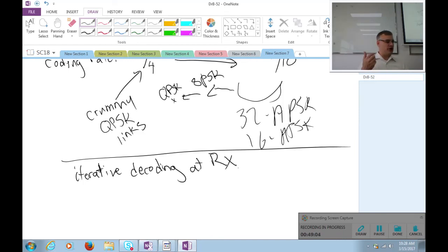And then if you apply your error detection and say, well, I definitely know I sent these bits in error, so I'm going to make a better estimate of that, then you can go back and correct your decision making, right? You say, well, this checks out. I did receive this symbol suboptimally, and it turns out I did actually make an error, so I'm going to correct those. And then I redetect and run that back through the decoder again.